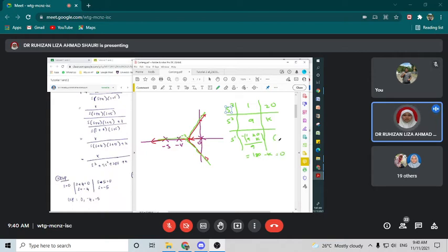Why? Because this can be your row of 0. You have nothing there on the third column, so here is 0. So the easy answer is 180. For the j-omega point, use your auxiliary polynomial.